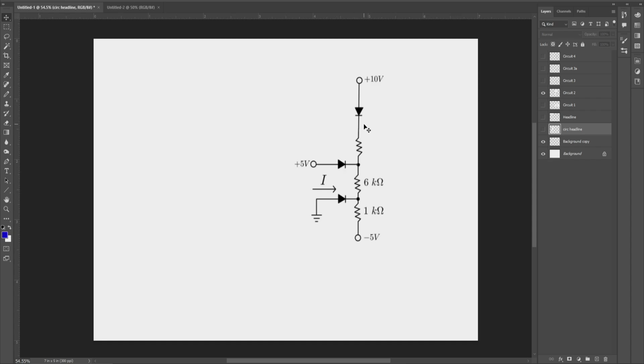First thing, what voltage do we have here? Can we use the voltage divider? We have a diode. Is this diode going to conduct? Well, let's see here. There's a plus, and it just goes to minus 5. This diode is forward biased. Yes, it is going to conduct.